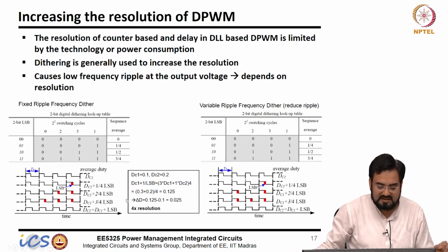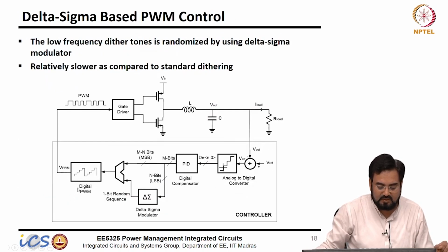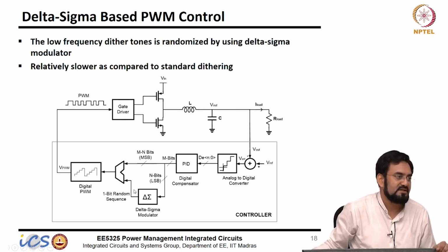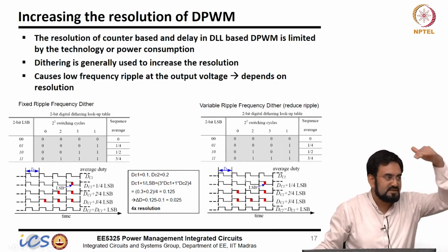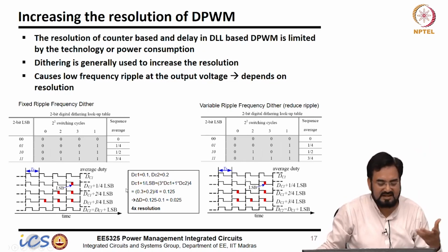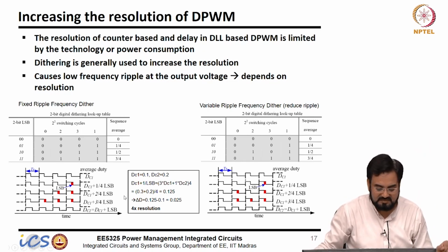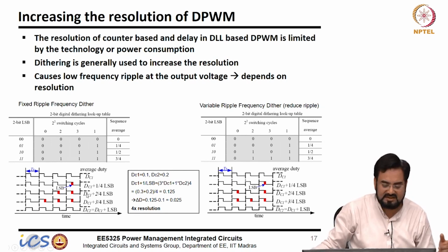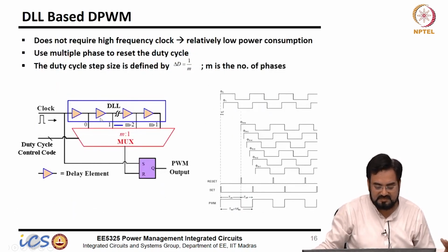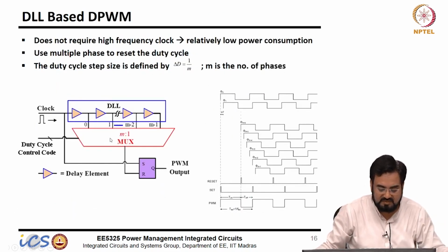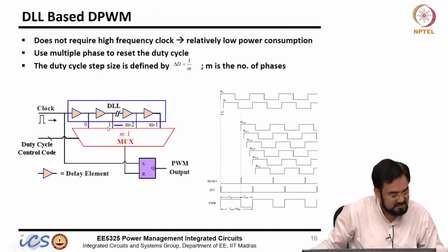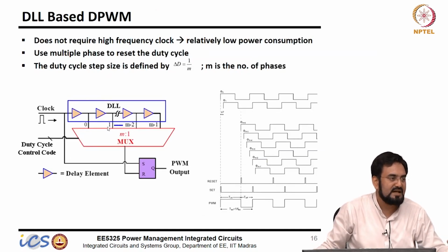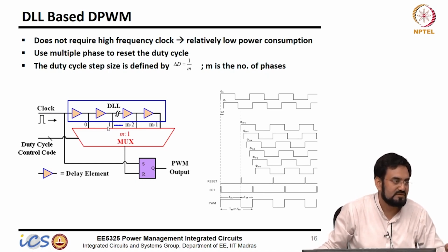So from each level, now you can think about it, this is doing a coarse DPWM, the fine control is coming from the delta sigma. So I have sliced, let's say, my DPWM in 8 levels. I mean 8 levels is actually very low, but you can think about again the same case where we were talking about the 100 megahertz clock or 7 bit. So 7 bit is also usually on the higher side. So let's say I have a 4 bit. 4 bit is 16 codes total.